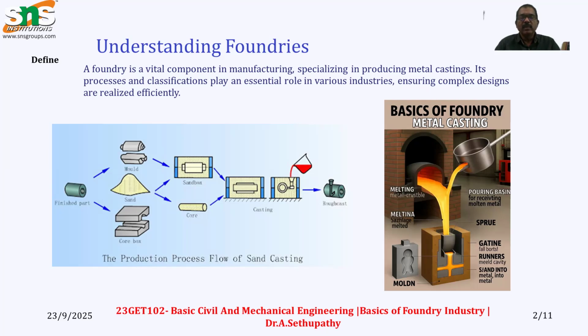Before we close the molding boxes, we provide an area for pouring the molten metal, called the runner, and the metal fills up and rises to the riser. After solidification, after two or three hours, we remove the molding boxes and get the desired castings. This is the casting process.